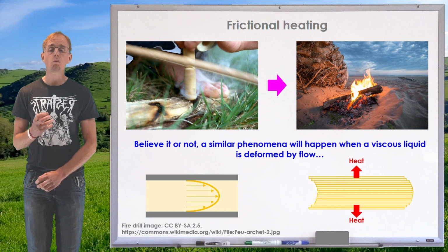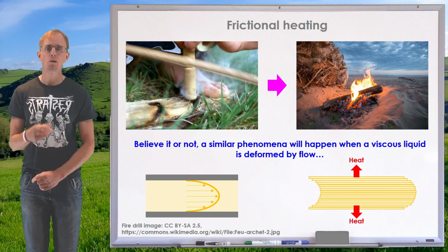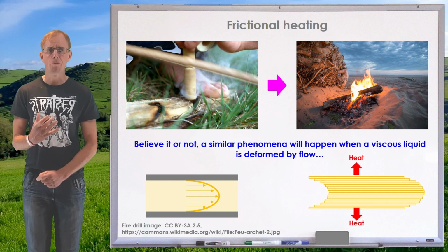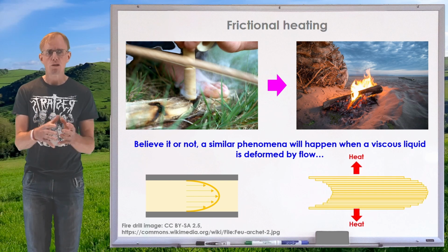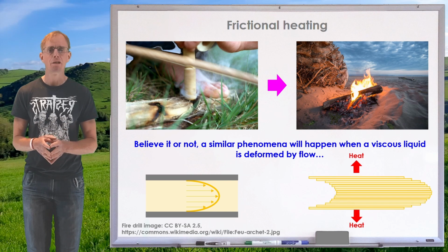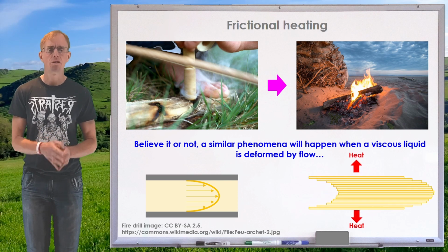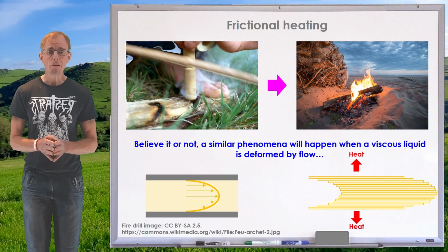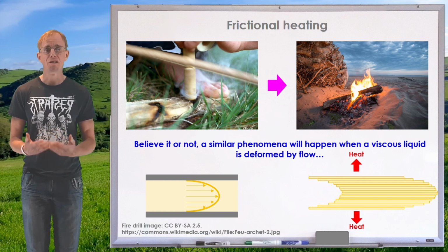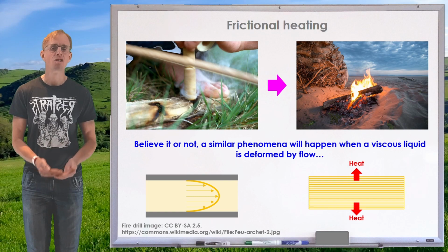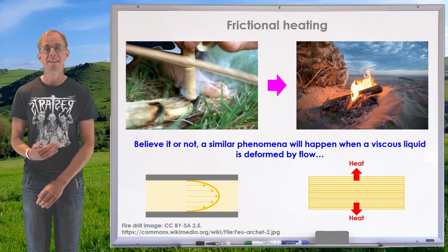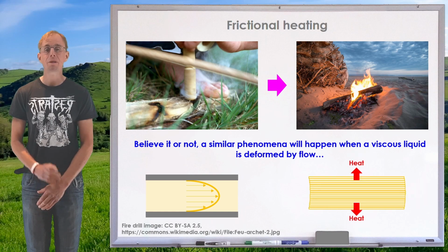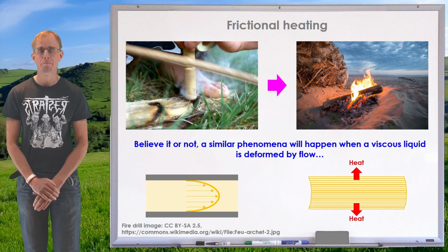And so what one finds is if you've got flows of highly viscous liquids through quite small geometries, capillaries or extrusion dies where you've got very, very fine details present, you're going to get viscous dissipation. And this can be a big problem because viscous dissipation generates heat, and heat changes the physical properties, particularly the viscosity of the material that we're looking at. So we need to be aware of this phenomenon.